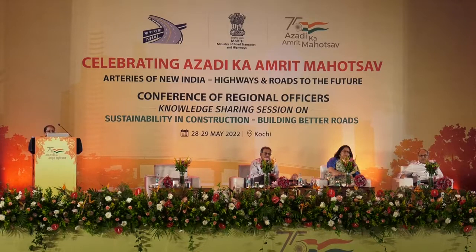Here of course the innovation which we did in the R&D center is to improve the shelf life and the stability. We are using virgin crumb rubber instead of crumb rubber modifier along with an appropriate additive system, which keeps the separation difference very low, and the elastic recovery is high in this particular product. So instead of 6 to 8 hours, you can still use it for 1 month or 2 months if you are storing it. These are the typical specifications of crumb rubber modified bitumen as per IS 15462.